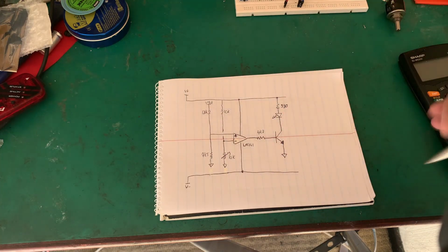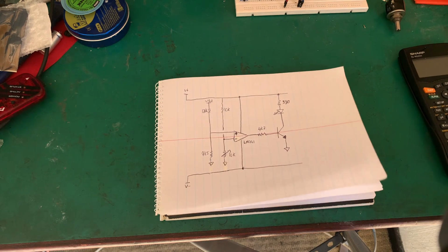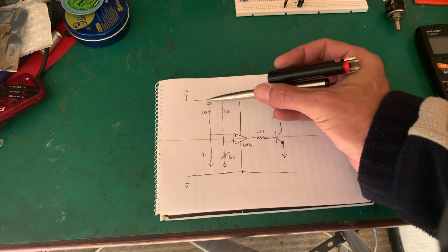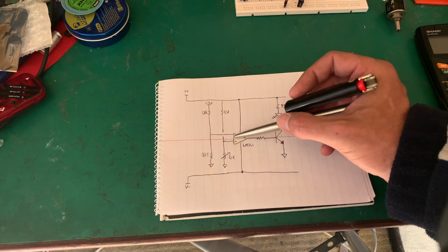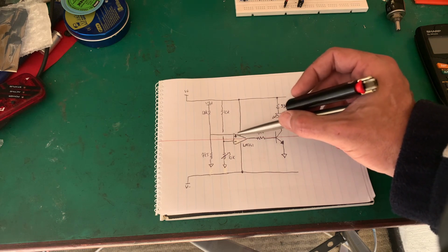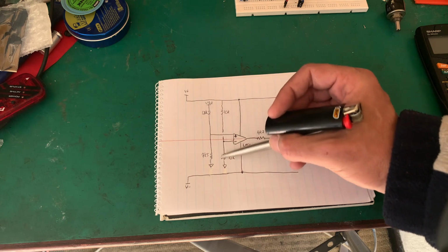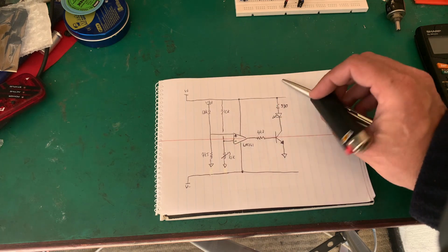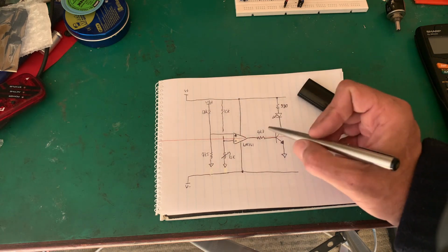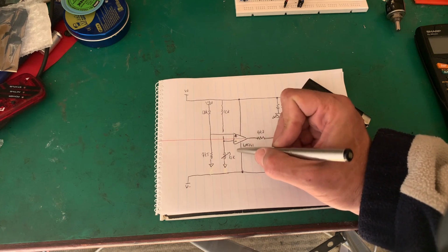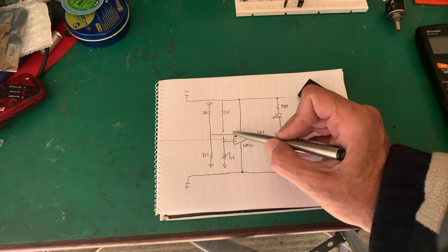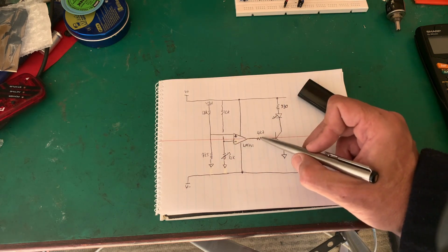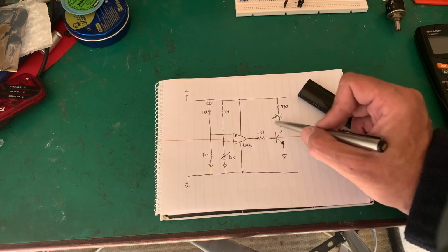This VBAT is basically from a solar power battery bank for a friend of mine, and we're monitoring the batteries there. And what we're saying here, you notice we're coming to that input there, the non-inverting input, and we've got this reference here that we can set, a 10K and a 10K pot. So we've got a reference point here. All we're saying is if that positive goes above that negative value, if this voltage here on the non-inverting input is above the inverting input, switch this output on, because we want to drive an LED.